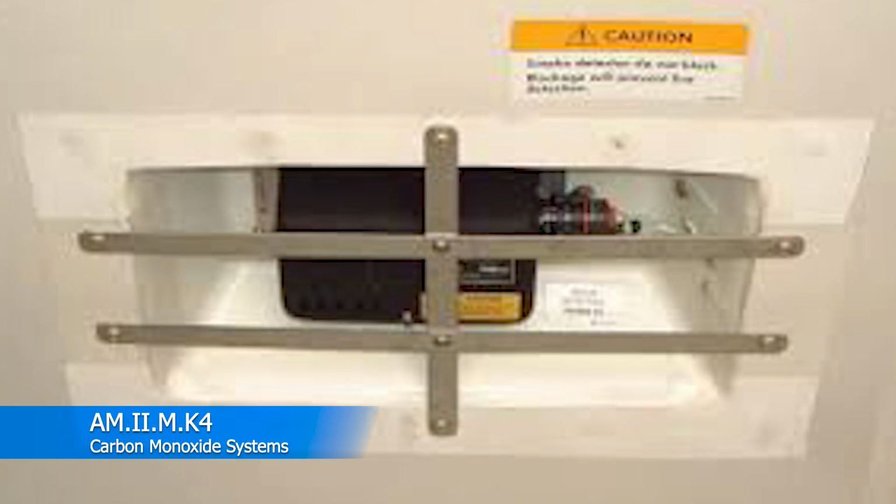All right. What you're looking at here is the cargo smoke detector inside of a 737. Notice that it has little bars over it to keep it from getting hit and keep things away from it, so that it can still detect the smoke as it goes through. This is a really common one that you'll see out there, and you might even end up having to change it. I don't think I've ever seen one actually go off legitimately. Most of the time something has happened to it, or it's broken, or something weird's going on. But yeah, it's a photo or light refraction type smoke detector.